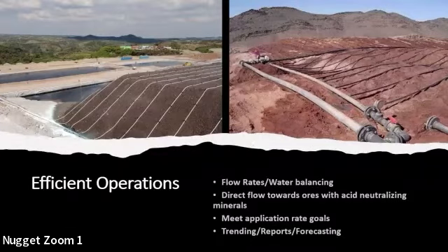So this hydrodynamic testing program included three ROM ore types from the pit. There was the siliceous potassic, which is the picture shown on the top. It's a coarser ore material. An argillic ore, which is on the bottom left, and then advanced argillic ore, a highly weathered ore. The testing program consisted of consolidation permeability, so performing saturated hydraulic conductivity measurements under load, which would replicate depths within the heap leach pad.